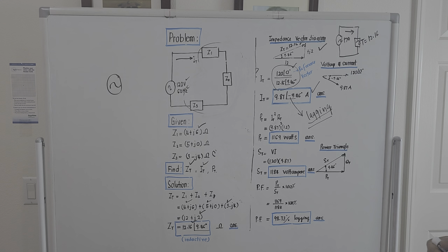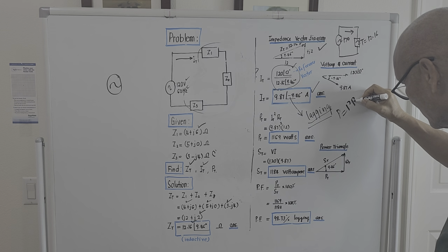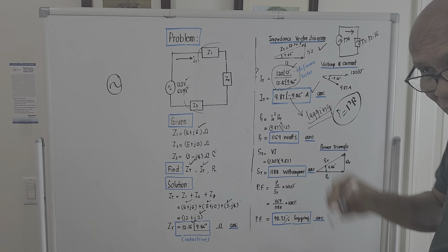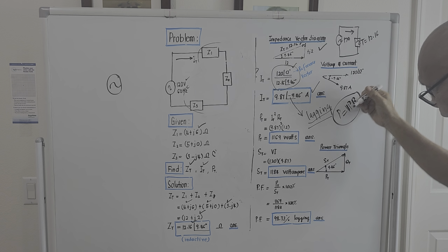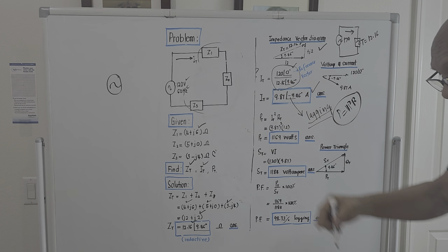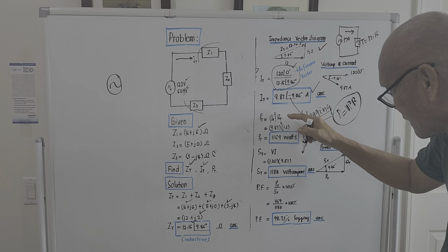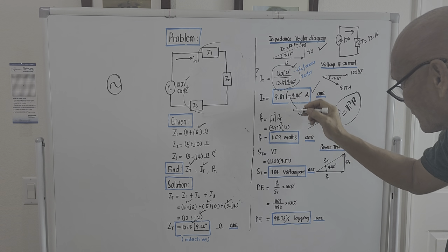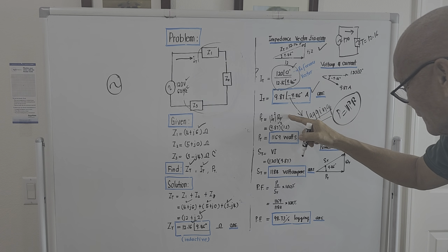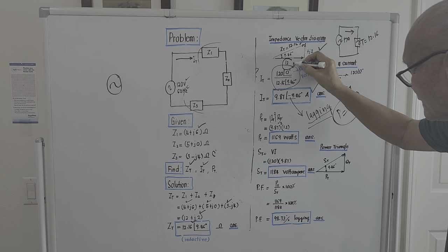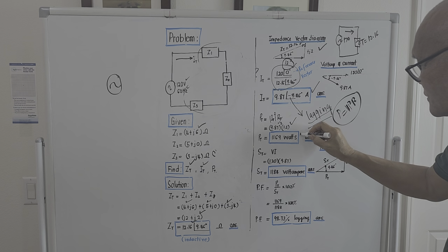For the computation of the total true power, we will just use power is equal to I square R. It's the same as in DC circuit. But we will be using absolute value here. We don't include the angle, okay? So in here, it will just be the absolute value square times R total. The total current, the absolute value of the current, is 9.87. So this is 9.87 square. R total is actually 12. The square of this times 12 is 1169 watts.